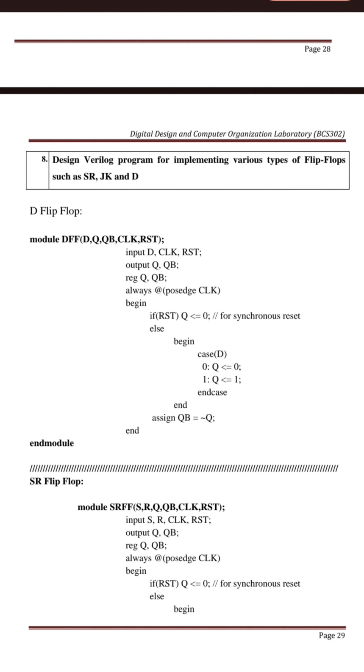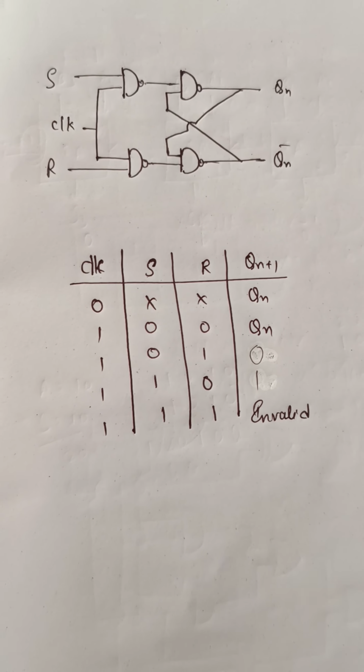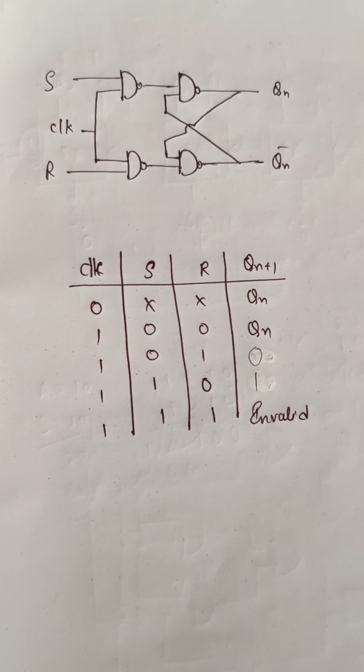Hello everyone, in this video we are going to learn the 8th lab assignment of the subject DDCO, that is to design a Verilog program for implementing various types of flip-flops such as SR, JK and D flip-flops. First we will discuss the SR flip-flop.